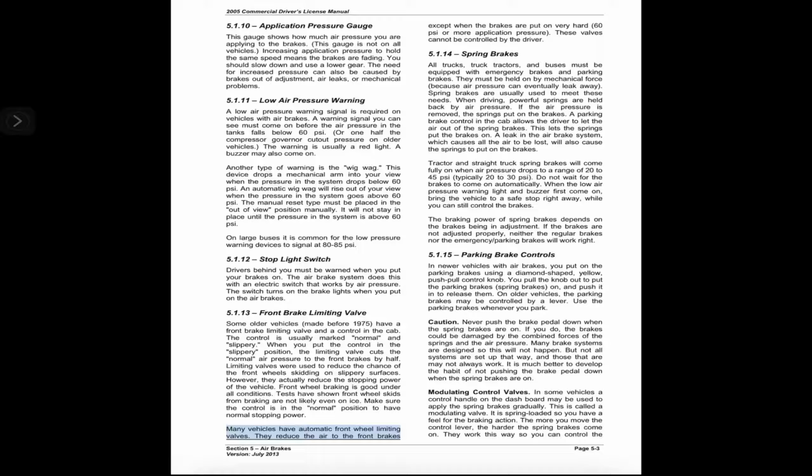Many vehicles have automatic front wheel limiting valves. They reduce the air to the front brakes, except when the brakes are put on very hard, 60 psi or more application pressure. These valves cannot be controlled by the driver.